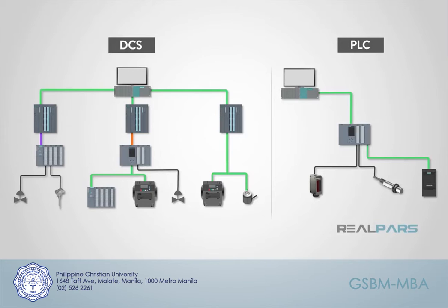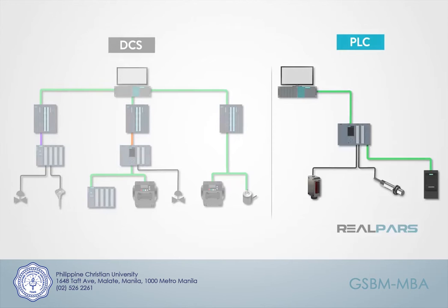In short, both PLCs and DCS have their place in the market today. PLCs would work best in a small production environment, where component failure, if no redundant system is deployed, is a small risk for the application, the budget is restricted, or the tasks and I/O count are minimal.